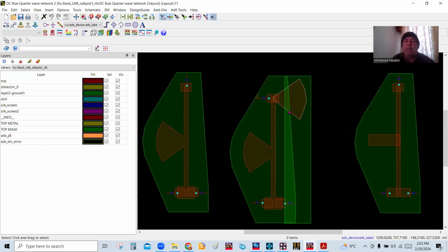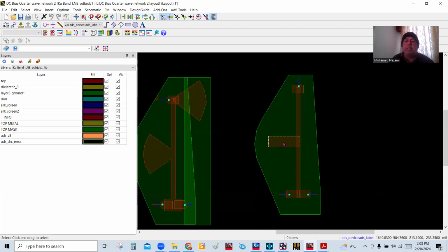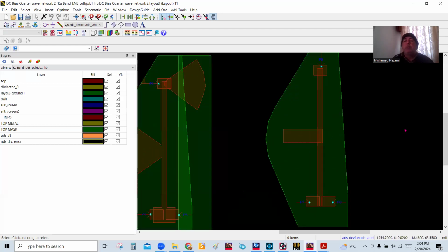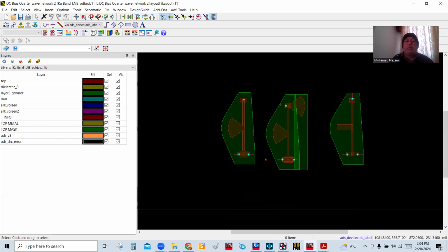What I'm going to do is copy this and stick in another radial stub. I copied this here and put in another radial stub. Then I got the same thing, except this is a different impedance line, which is just an open stub. And I want to see the frequency response of all of these. So what I did, let's go to the RF Pro for this.